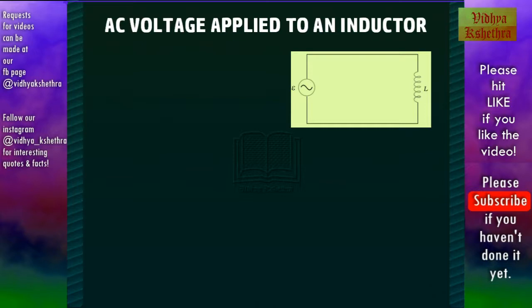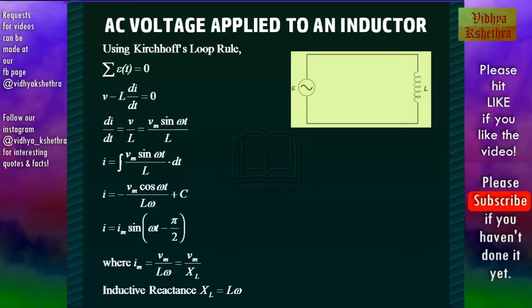This shows a circuit with an AC source applied across an inductor. An inductor does possess some resistance, but we can neglect this. Now using Kirchhoff's loop rule, we can write sigma of E of t is equal to 0. That is V minus L into di by dt is equal to 0. Here L is the self-inductance of the coil and di by dt is the rate of change of current, which induces the emf due to self-inductance.